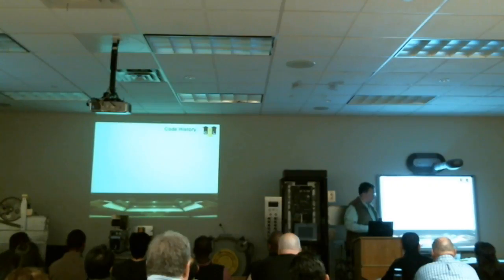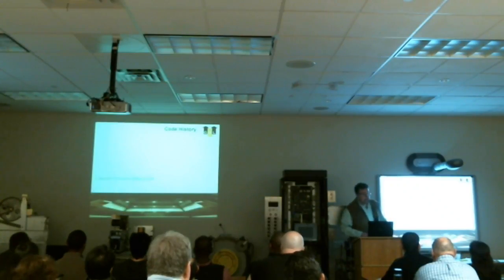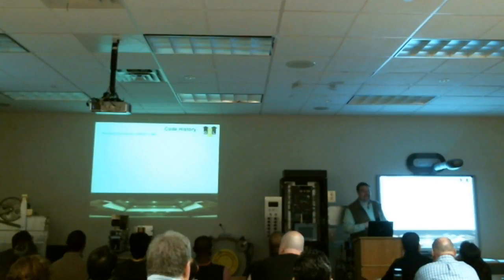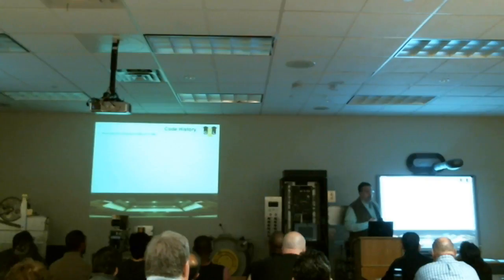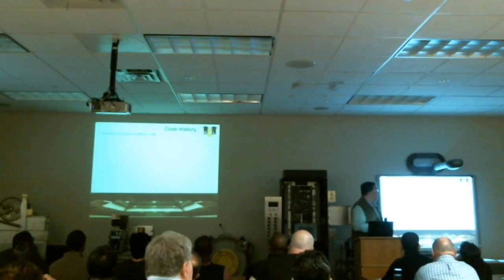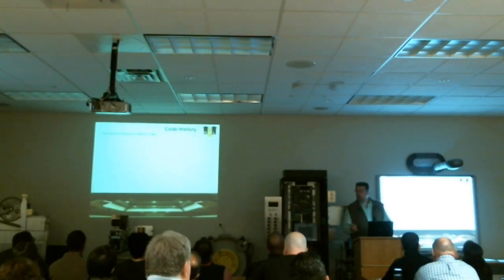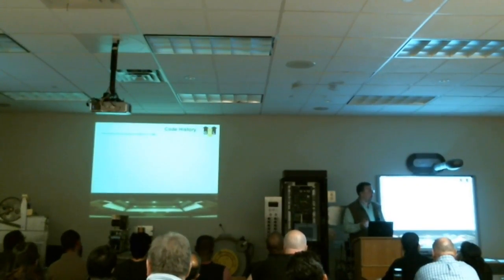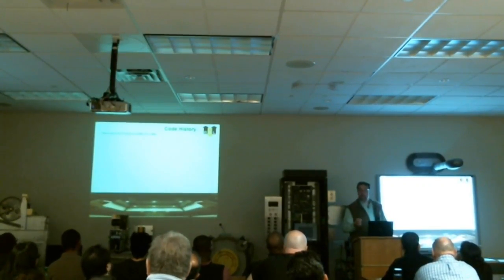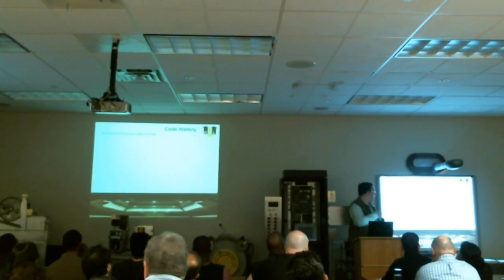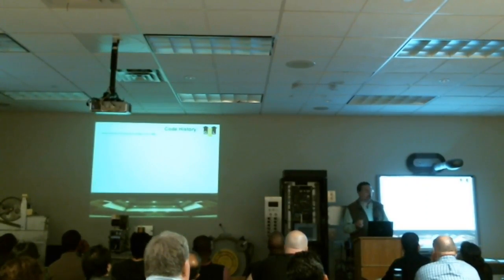A little bit of code history here. This is kind of an interesting fact. The door lock monitoring actually was instituted in 1996. Now, ASME, not sure if all of you are familiar with, stands for the American Society of Mechanical Engineers. They're the ones who pretty much dictate the elevator code. They publish a new code every 3 years to tell you what you need to do in order to safely run an elevator. So they instituted in 1996 door lock monitoring, the requirements we just had gone over.